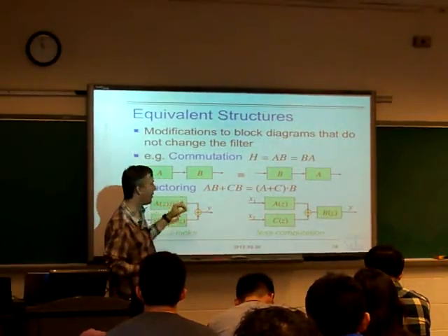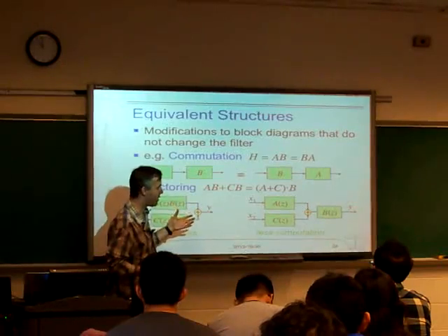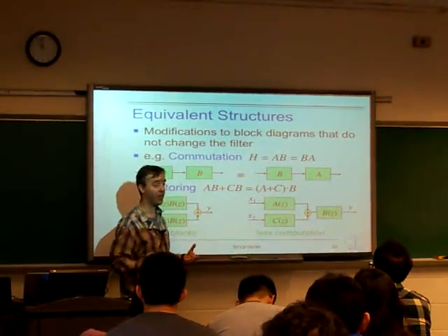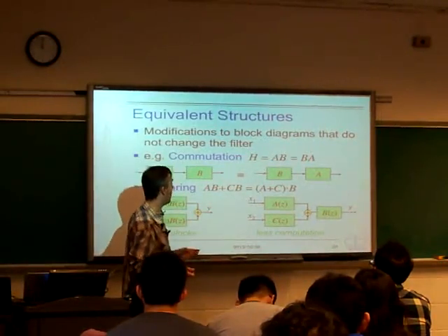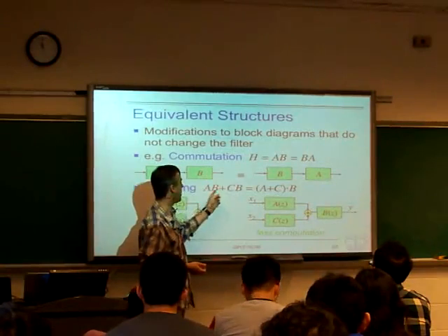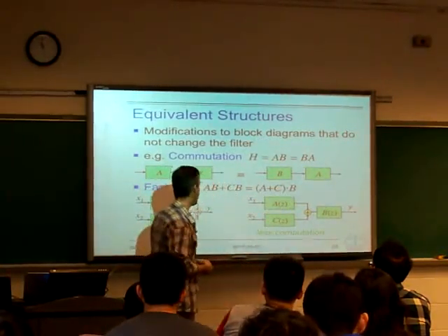We know that convolution is distributed over addition, which just means that multiplication is distributive over addition in the Z-transform domain. So if we have something like this, where we have the sum of two systems with a common factor, we can take out that common factor and just apply it to the sum.